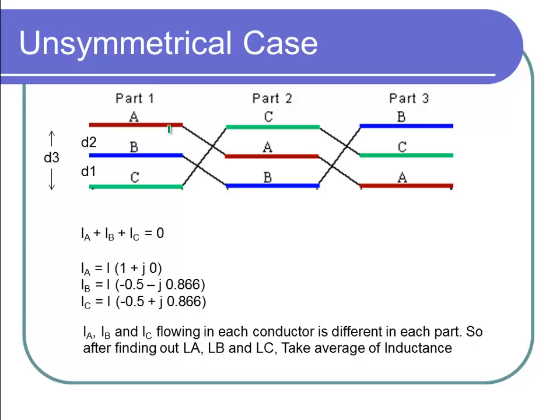We know very well if the inductance varies among the conductors, definitely the voltage drop on each conductor also varies. We are not having a small distance. Our transmission lines are in terms of hundreds of kilometers, and finally at the receiving end the voltage becomes unbalanced. The consumer will not get a constant supply. That is, an uneven voltage will be there.